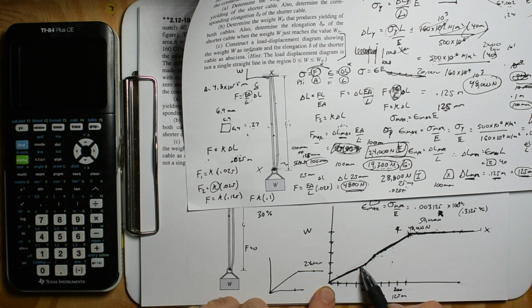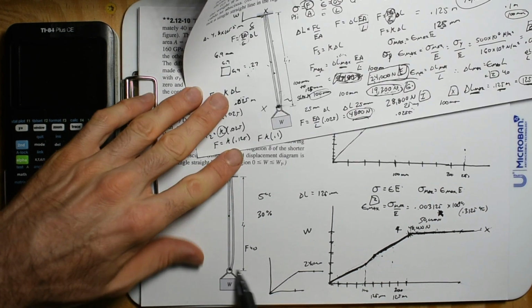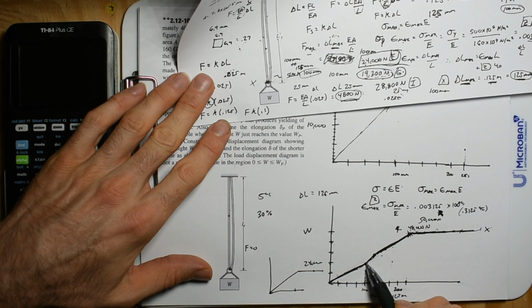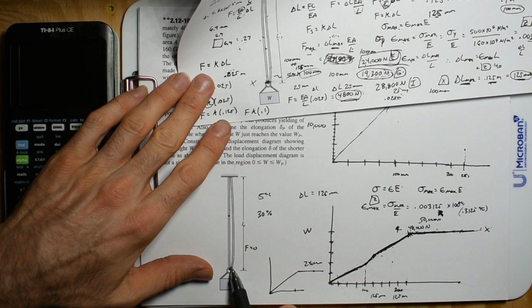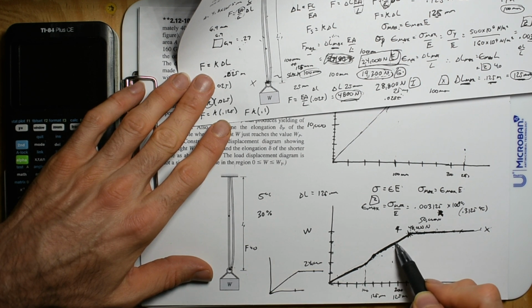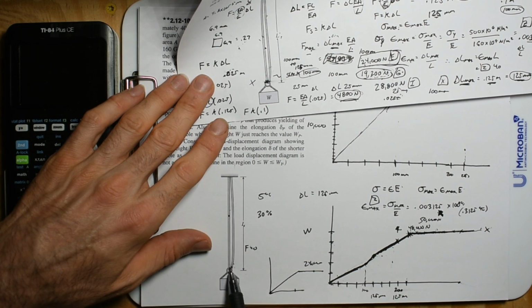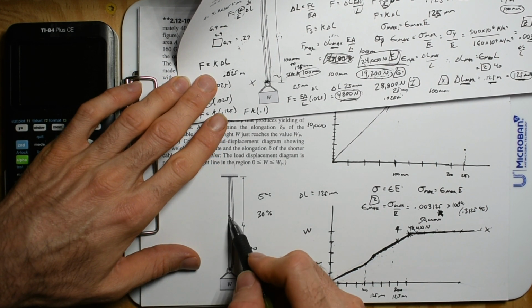You know what I mean? Where here you have a cable that is stretching to its plastic load, but then it's backed up by something that's elastic. You know what I mean? And then you don't want to pass that point. But it's okay to be in this range with this design. Stuff like this gets designed all the time where one member hits its plastic point.